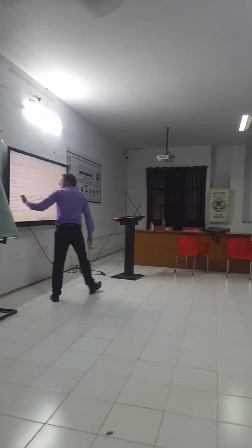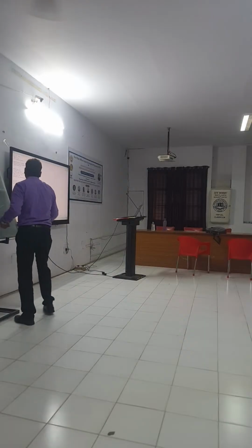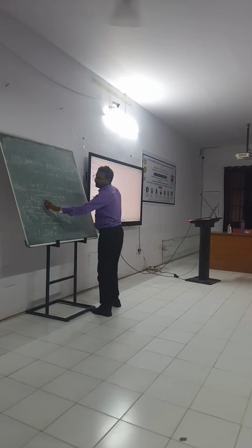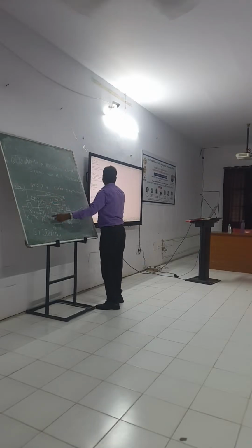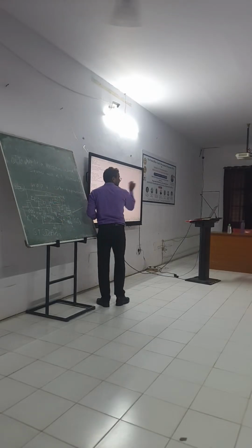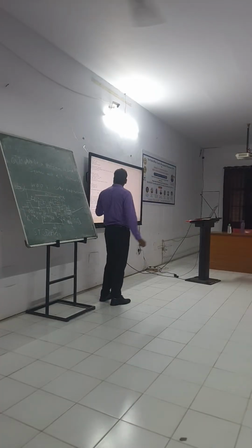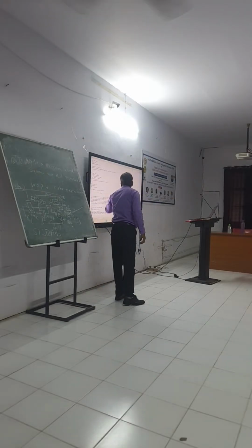So this is the netlist. The netlist means how it is connected. See, MP1's drain is connected at L. Its source is connected at VDD, and the body is also connected at VDD. It is a P type, so it is PMOS. Its width is W, because in the library W is mentioned as 60 nanometer. L is L, that is, its length is 60 nanometer. And the other parameters, like lambda, are common for all.